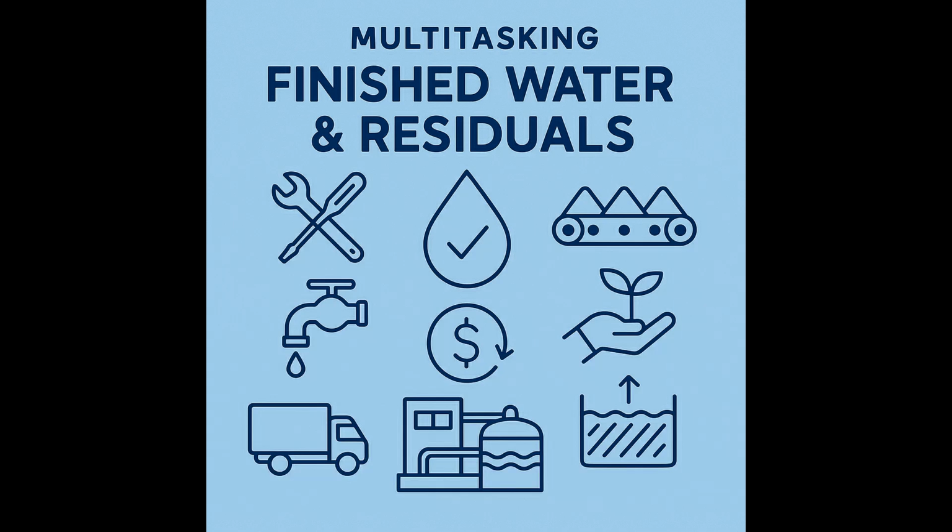So the bottom line for that medium-sized plant considering this route? The bottom line is, prove your chemistry first. Bench and pilot tests, including PFAS. Engineer robust systems, automation, scales, storage to minimize labor risks and hauling disruptions. And work closely with DEQ to ensure a clear, defensible VPA permit path, keeping a very close eye on PFAS developments. If you do it right, meticulously, it can be cost-effective and environmentally sound. But if you approach it casually, it can easily spiral into a major staffing, compliance, and PR headache.